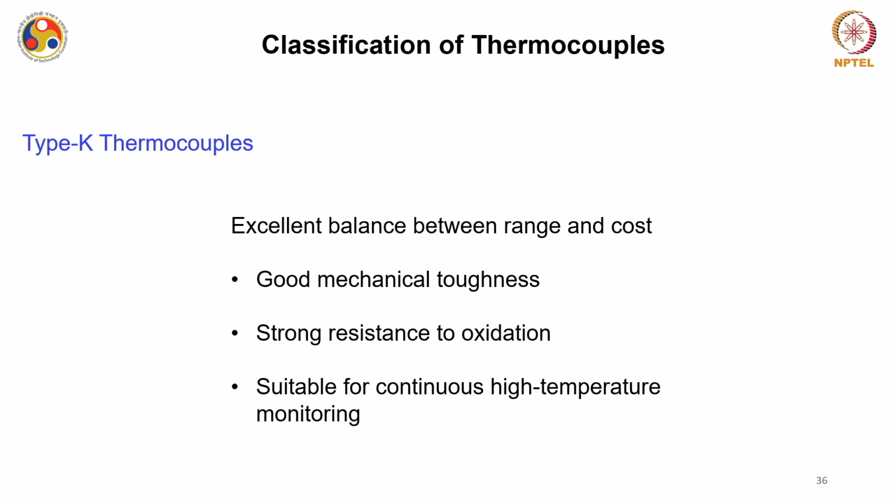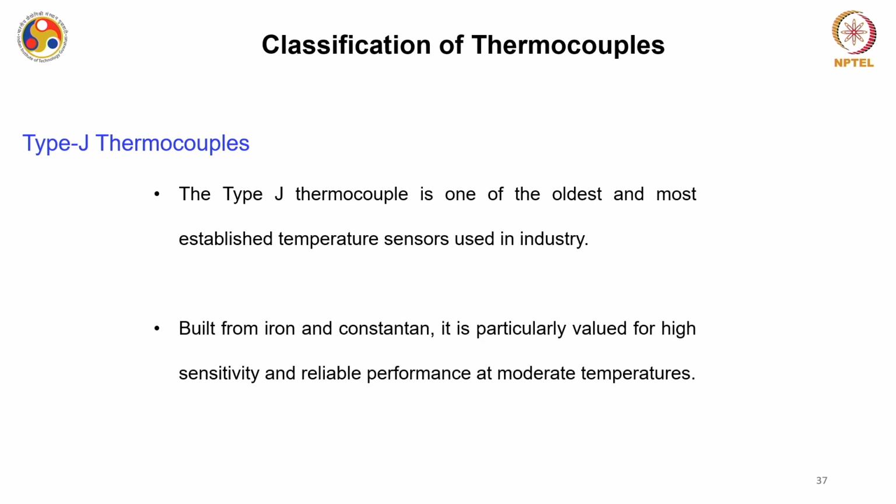So you have good mechanical toughness because you have seen what kind of alloy is used for the fabrication. They have a strong resistance to oxidation, and that's why they are preferable for oxidative operations. They are suitable for continuous high temperature monitoring. And of course, like any other thermocouple, they are self driven or self powered.